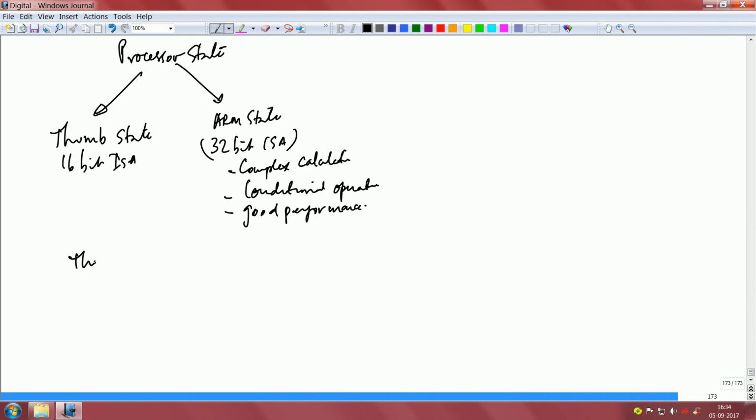Right. Just to continue on Thumb 2, there are a number of new features. Let me just take an example, ARM architecture V7, where you will get Cortex M3, M4, all of them, with a large number of new features, and these include hardware divide, which I already mentioned, and multiply for data crunching operations.